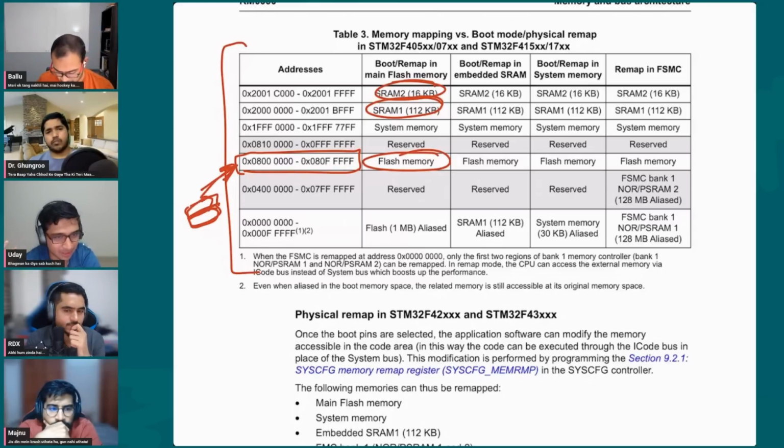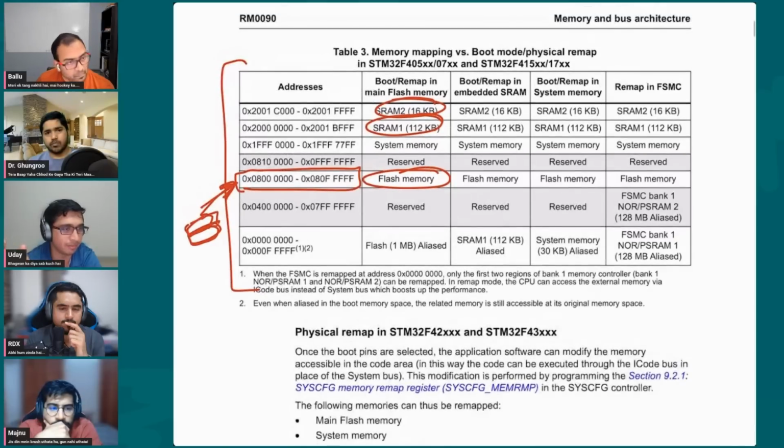You can completely go out of RAM, doing everything from RAM, and that's where we had the third option as RAM as well, where we can boot the device completely out of SRAM. Right, but then SRAM would hold the values only until there is power supply. Exactly. In which case, if the power is gone, the code is gone, the memory is wiped out.